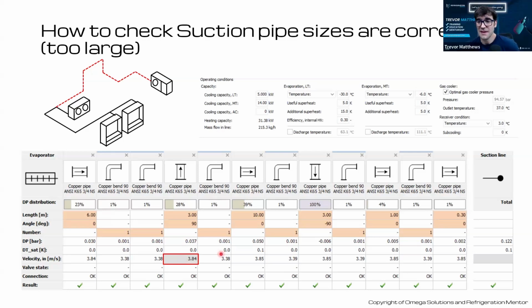Yeah. And then we got another question: is Cool Selector 2 a good software for pipe size? Yeah, it's a great one. It is a good one if you want to do single piping, so it does take a lot longer versus micro pipe. You use micro pipe, it takes all your piping. So you could have hundreds of pipings, and you change a pipe, it will effectively change all the design, or at least notify you what pipes are now undersized, oversized, things like that. So that's the difference between micro pipe and Cool Selector 2 or another sizing software out there. Great question, William.